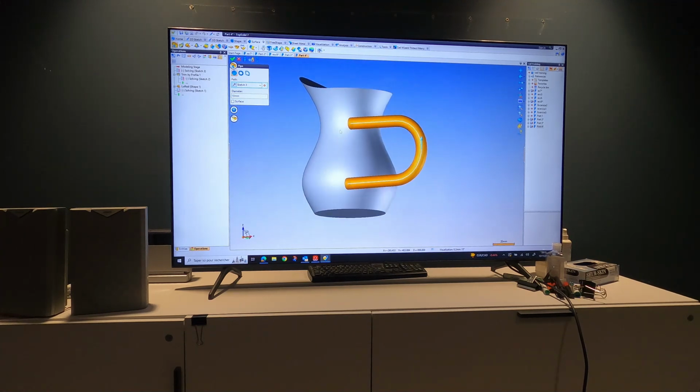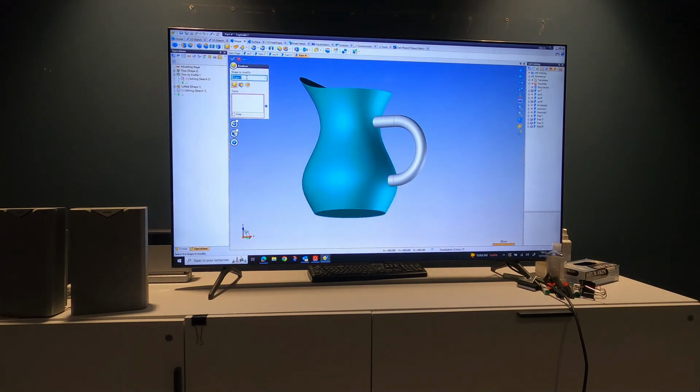And the diameter is 10, that's fine because they ask radius 5. Okay, so you can accept this. So that's done, because it's solid. Now you can do the boolean union. Make only one shape. So my shape is the original, my tools is this, and that's good.